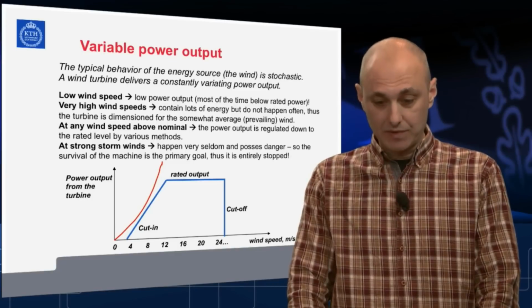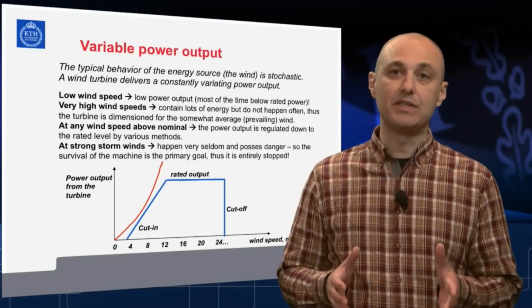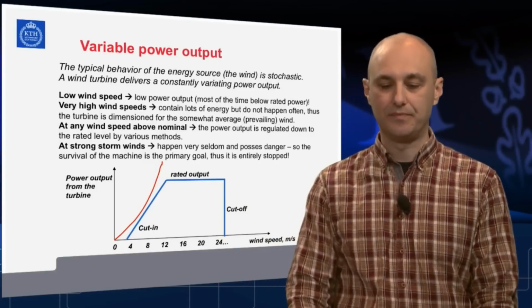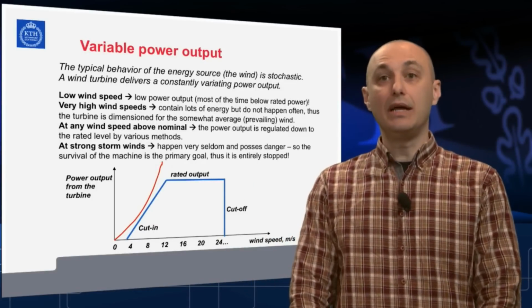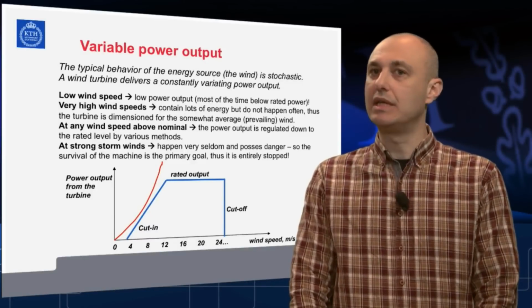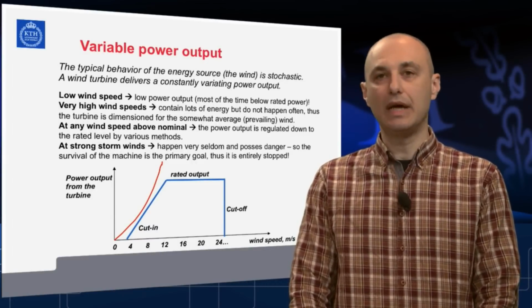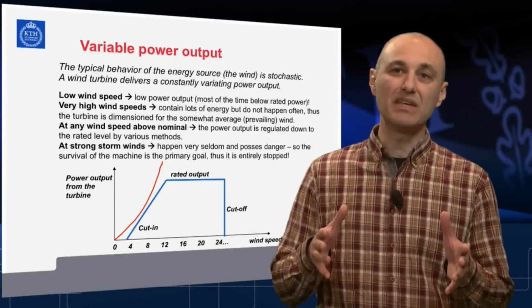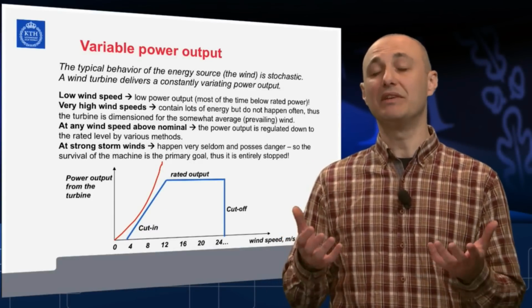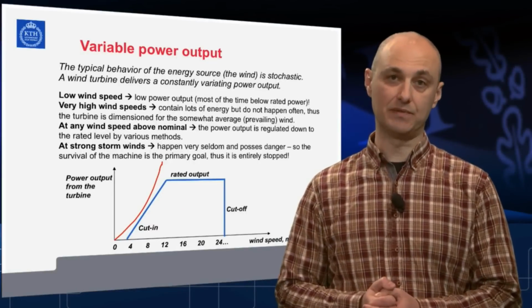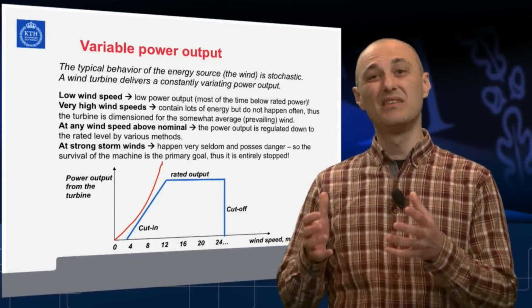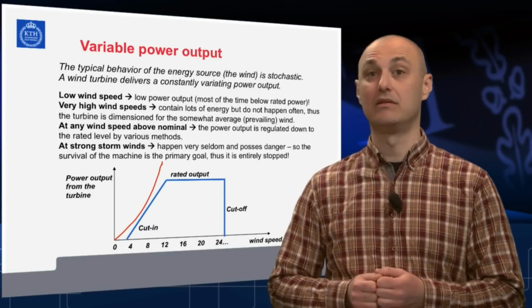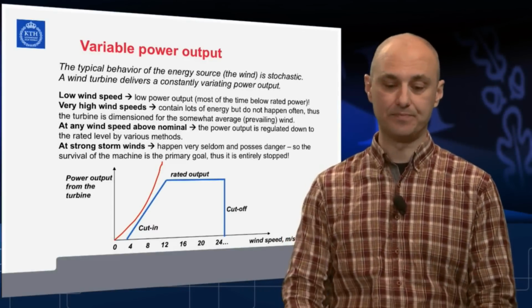At very high winds, there is a lot of energy in the wind, and it would be nice if we could efficiently use it, convert it, deliver it. However, high winds, good energy winds, don't happen very often. They occur quite seldom. The wind turbine doesn't need to be dimensioned, built and rated for the high winds. We would rather dimension it for the average, most prevailing wind speeds.